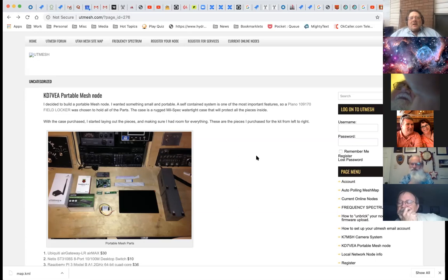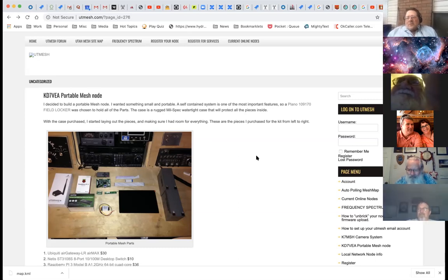Any other questions? Yes, I have a question. I'm to the northwest of Murray, and so I'd probably need, instead of an omni like most people in Murray, I'd need a directional to tie into that. Is that correct? Well, if we had a sector antenna on top of the hospital, for example, and you had a directional antenna like a Yagi or something, I think you would be able to tie in just fine over a distance of 20 or 30 miles. Okay, so I'm only 6 away, so you would be fine, right? Yeah, right.